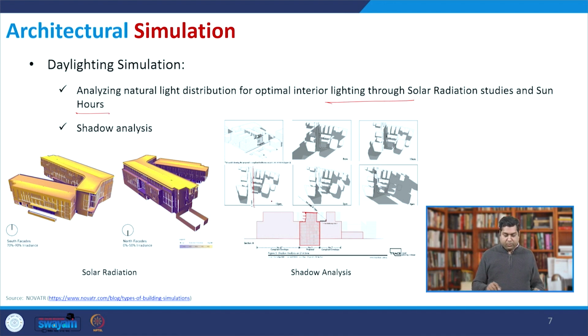Here you can see, under different heights and different times, how this shadow analysis can help to demarcate those areas. Like if you want to make a pathway, or a sitting place in an office building's surroundings, in such cases you can do the simulation and then accordingly change the massing, the solid, opaque part of the building or maybe the transparent part of the building. For daylighting, simulation is very effectively used.